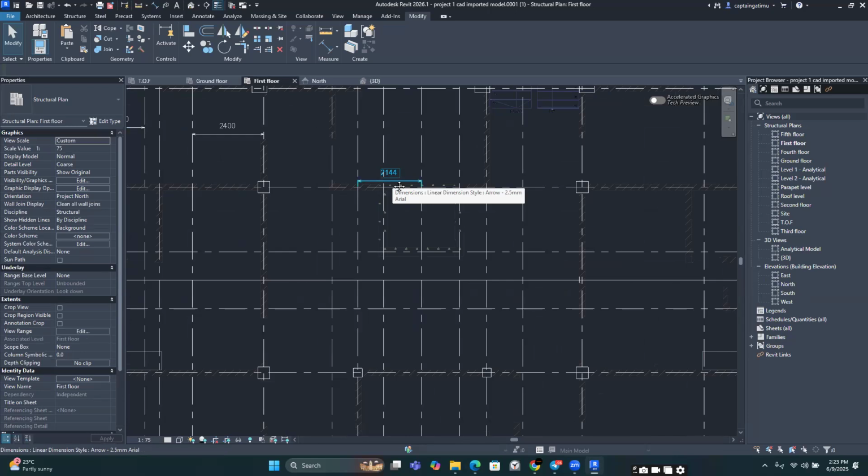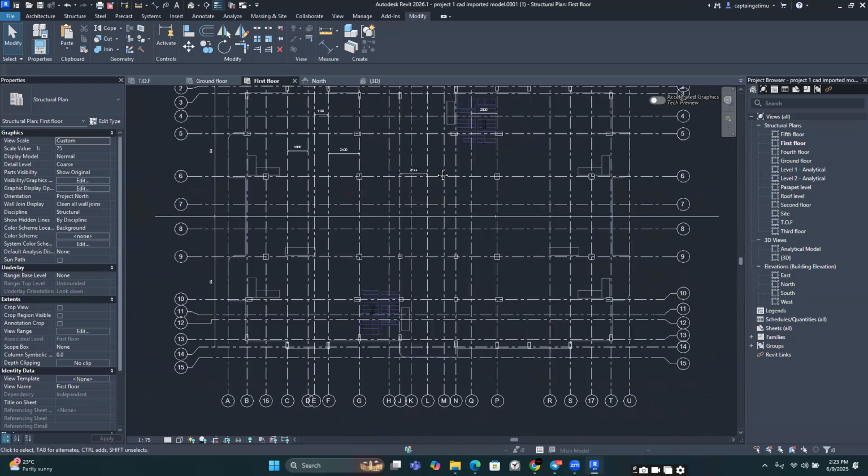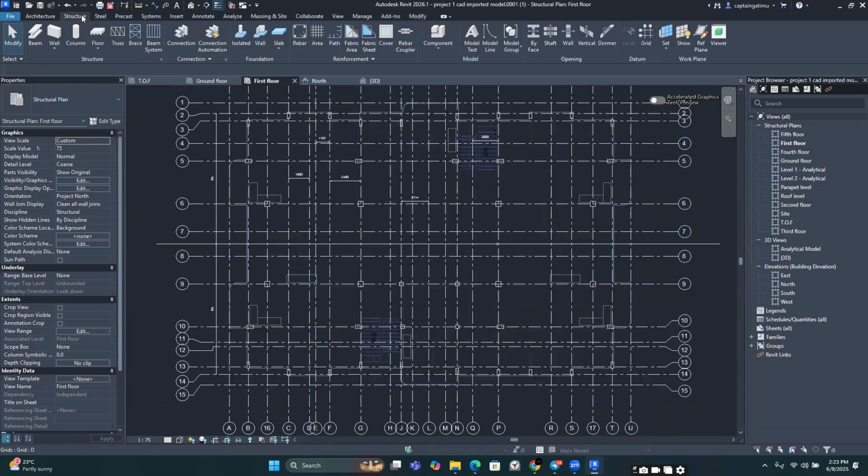All right. So let's place them. So I hope you can see where we have these particular shear walls here, the 4 of them. That's where we are going to model those shear walls at. So to model shear walls, we are going to go to the Structures tab. I hope you are now taking note of something. Whenever we want to model a structural element, the first place you are going is the Structural tab. And then from the Structural tab, you're going to select Wall, and ensure you select the Structural Wall.